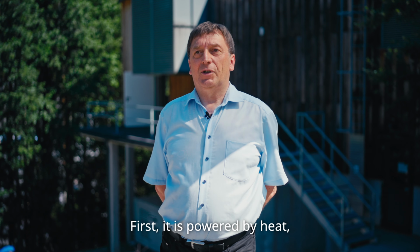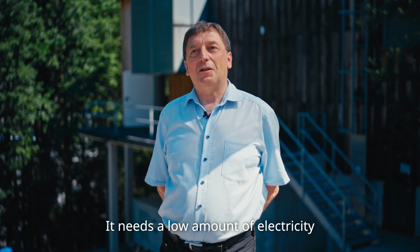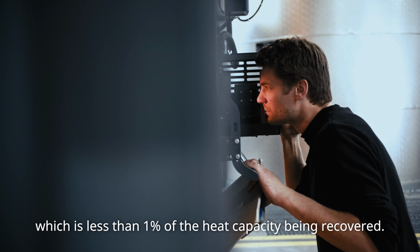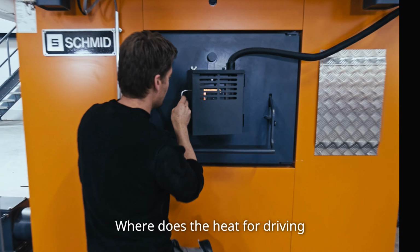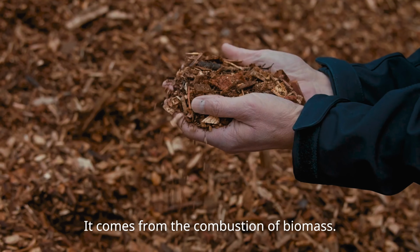First, it is powered by heat, not by electricity as compression heat pumps are. It needs a low amount of electricity for the circulation pumps of its liquids, which is less than 1% of the heat capacity being recovered. Where does the heat for driving the absorption heat pump come from? It comes from the combustion of biomass.